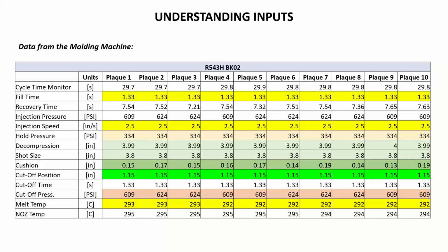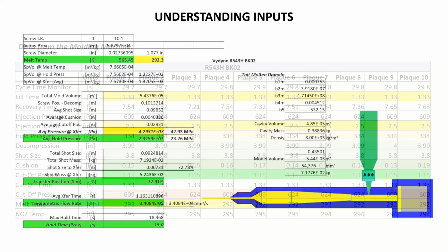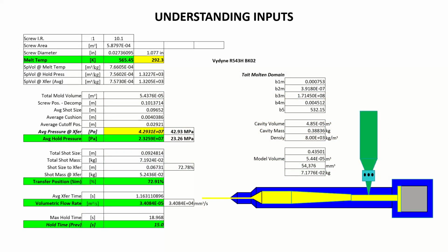Okay, so you'll get different effects on the tonnage. So in the spirit of having compression in this process, I took the tape parameters for this material and used them to get the density and account for the compression of the material at the different locations, so that essentially I'm accounting for my shot size not just as a volume but as a shot mass, to represent the same mass that will be in my model in the end.